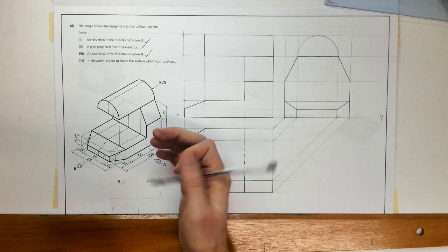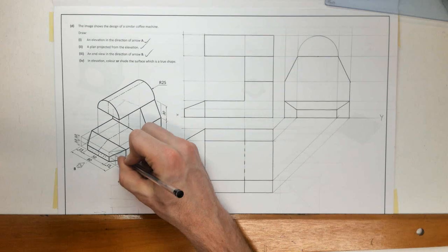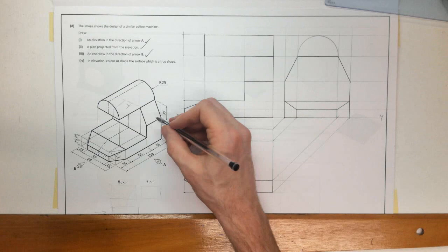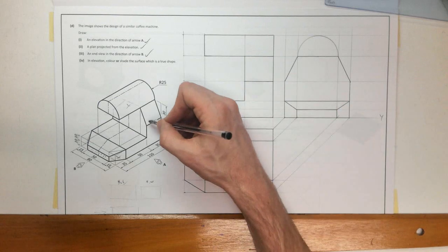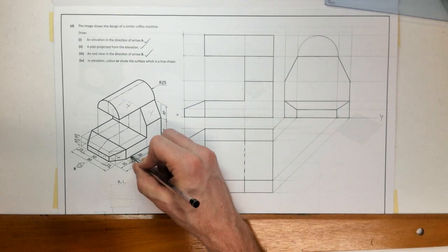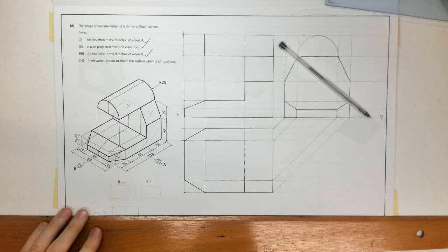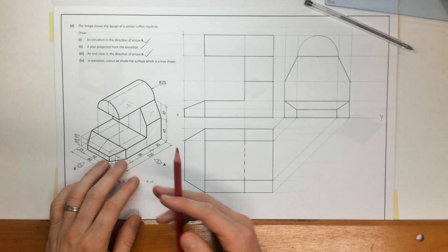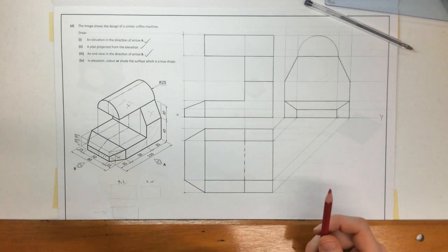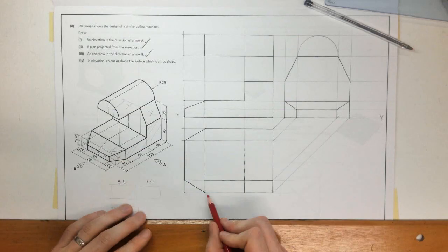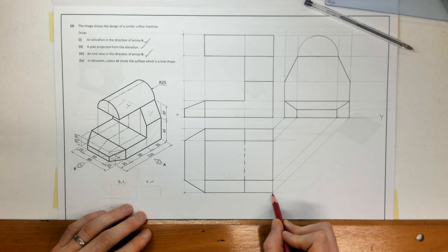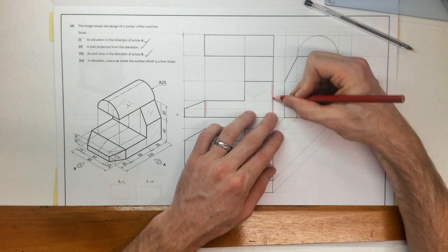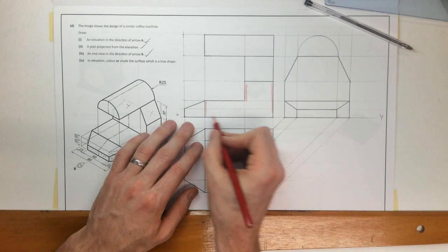So this one is sloping away from me, so it's not that. This is a curved surface, so it won't be a true shape. This is also sloping away from me, and here, that surface there, that is going to be a surface that we're looking perpendicular to. Okay, we're looking straight at it, and the reason I know we're looking straight at it in elevation is it appears as an edge here in plan. Okay, and I'll actually highlight that as well for you. So let me just shade that very quickly.